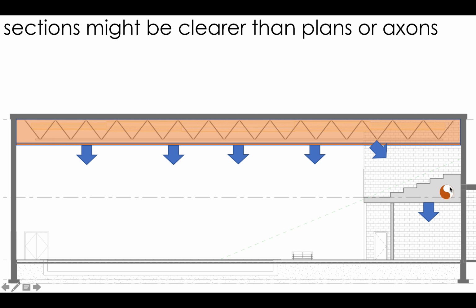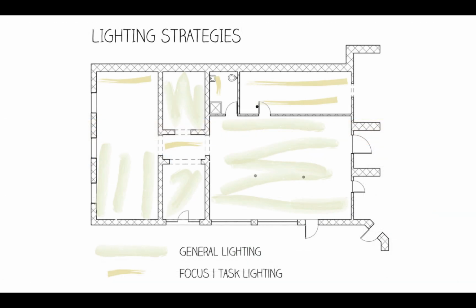Well, this symbol, by the way, is a symbol for duct that is cut through. Hopefully we will run the ductwork under the seating. You see how there's enough space, at least in the diagrammatic way. And then the air will get blown into those spaces below. Presumably there will also be a return duct, which I probably should draw in there as well. And you should do a section for anything that you think is appropriate. I'm showing you the major ones, the ones that are kind of required, but you can absolutely do it anyway.